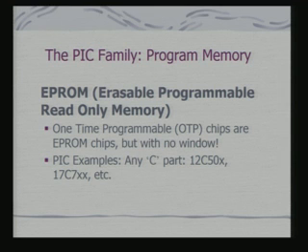In fact, one-time programmable chips are EPROM, that means they have EPROM, but there are no windows. Why no windows? Because I can use the window to erase a program through ultraviolet light. And if there are no windows, then effectively I cannot erase that. So, I get one-time programmable. In fact, they are something like a factory programmable chip.